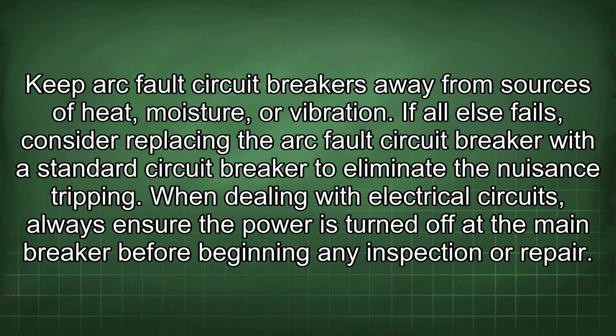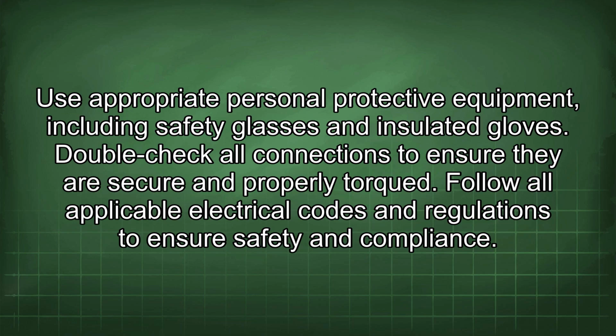tripping. When dealing with electrical circuits, always ensure the power is turned off at the main breaker before beginning any inspection or repair. Use appropriate personal protective equipment, including safety glasses and insulated gloves. Double-check all connections to ensure they are secure and properly torqued. Follow all applicable electrical codes and regulations to ensure safety and compliance.